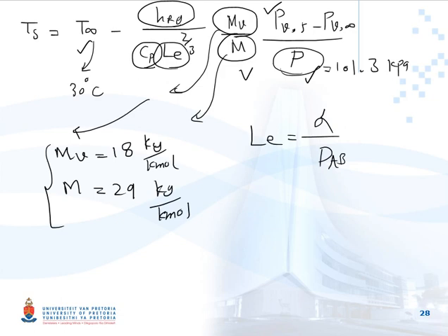The problem is that we have the dry air temperature, but we don't have the surface temperature to find the properties of the mixture at the average temperature, T infinity plus Ts divided by 2, and after that find them based on that temperature.